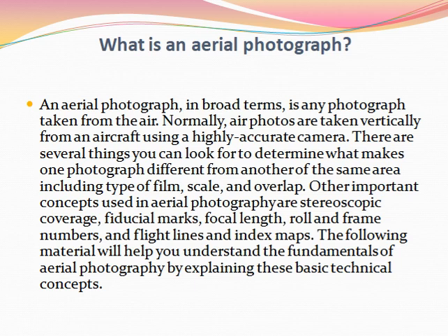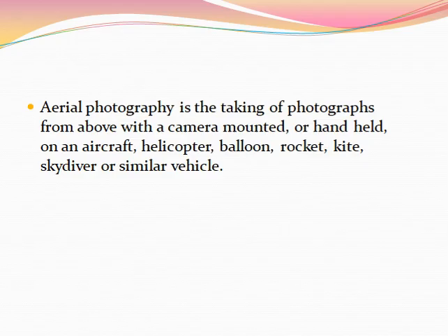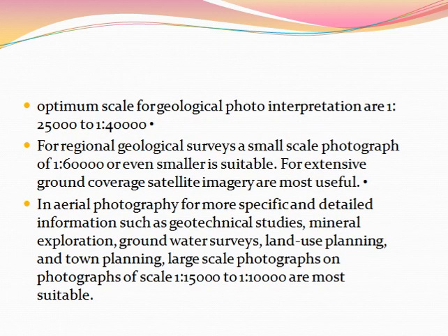Landforms, vegetation, land use, roads and tracks can be directly seen in aerial photography. Soil properties, geology and other land properties require indirect interpretation. The scale of map used is 1 to 10,000 to 1 to 50,000.